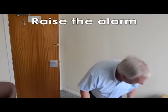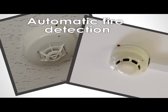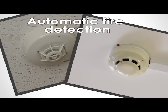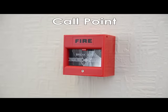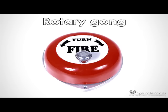Tip 2. You need to raise the alarm by alerting people in the immediate area, and if fitted, activating the fire alarm from the nearest fire alarm call point, or red box. Many fire alarm systems will have automatic fire detection in the form of smoke and/or heat detectors. Others will require you to break the glass of a manual call point. Some smaller buildings may not have a fire alarm. In these cases, there will usually be an alternative means of raising the alarm. For example, a self-contained howler, such as a rotary gong or air horn.